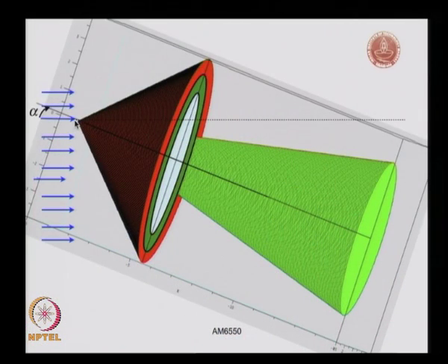If you look at this dotted line, you can see that the symmetry is lost. So, we will not have flow coming in here, distributing equally in all directions and moving along the surface of the cone. We are not going to have that. Previously we had straight streamlines coming in, deflecting and going past the shock structure here. Now, these are going to be curved; they are not going to be straight streamlines.